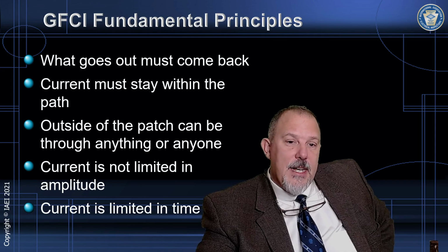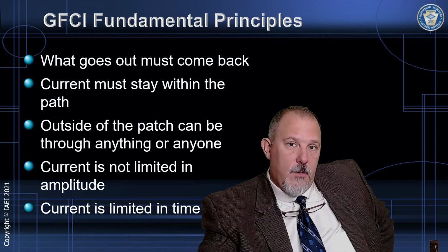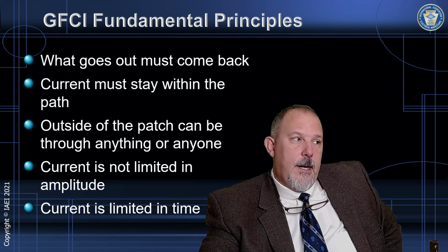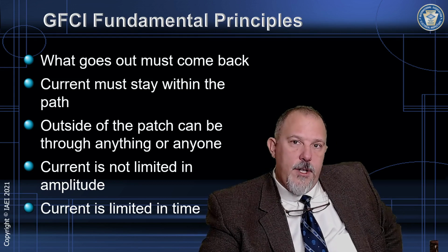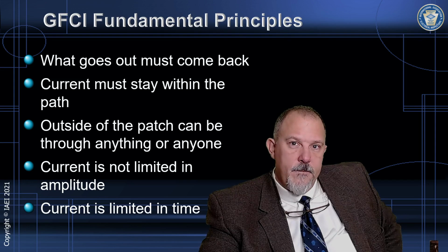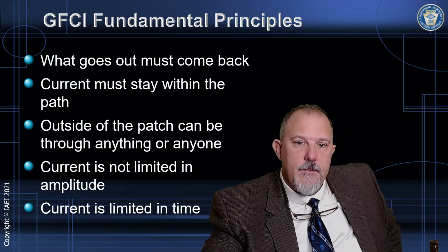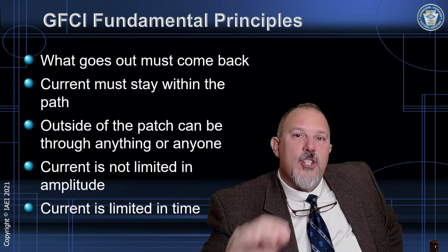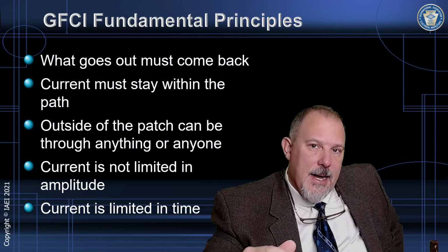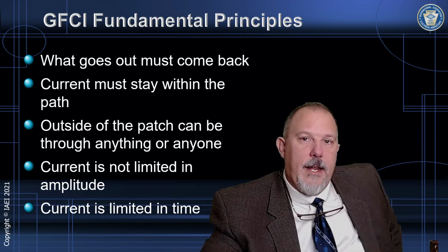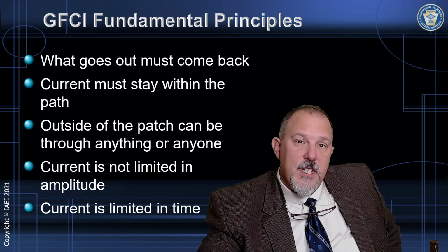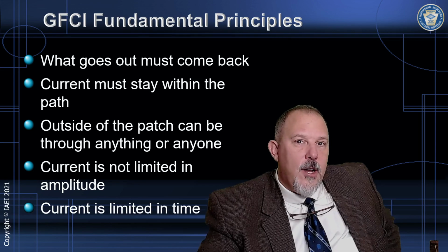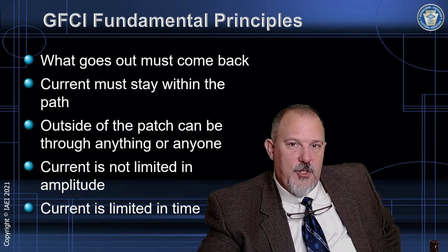When you're on a GFCI circuit breaker or receptacle, there was nothing in that picture that showed anything that would limit the amount of current that will flow through your body. What I am doing with a GFCI receptacle or circuit breaker is only limiting the amount of time that I let it pass through your body. So a GFCI receptacle or a circuit breaker cannot change the magnitude of current that will pass through you.